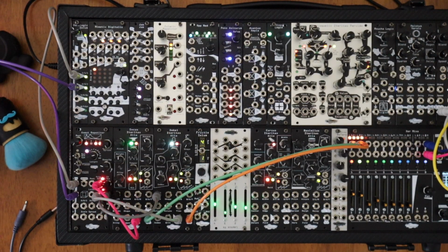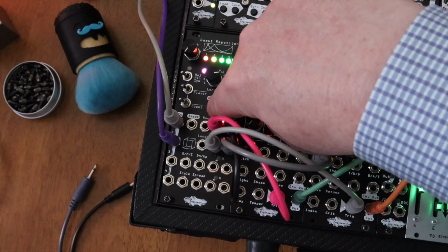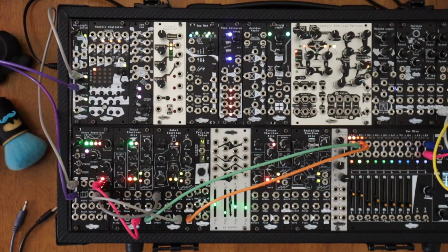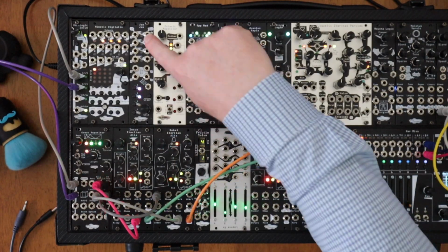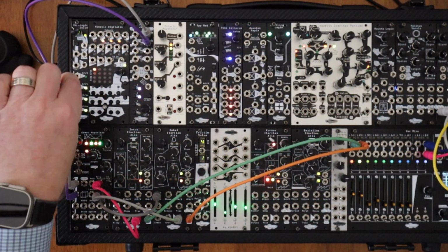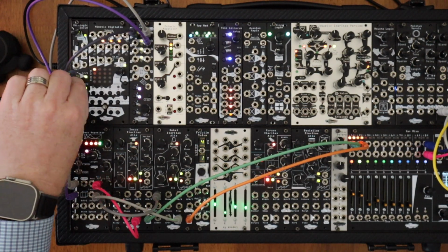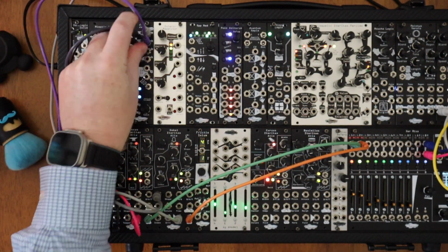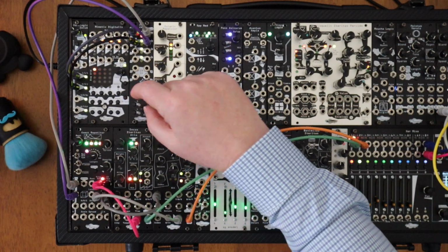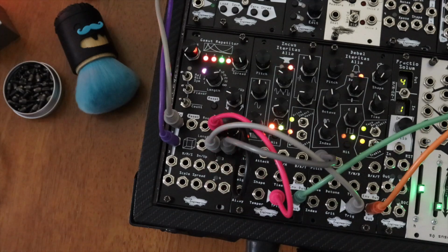This gives you a 50% pass-through on the trigger outputs. Holding it down again changes it back. If you want to adjust how much or how little triggers pass through, add the jam in between your clock signal and Gamut Repetitor. Set jam to random mode, add a trigger signal, and turn the encoder. To the left, fewer triggers pass through, and to the right, more pass through.